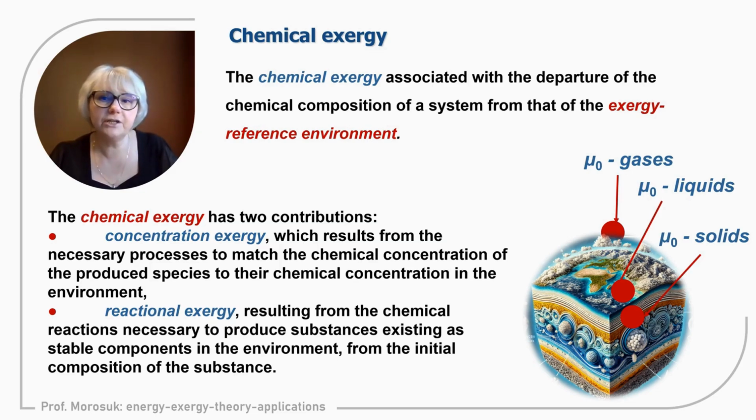Concentration exergy is associated with the work that can be produced when the system is brought to equilibrium with the environment, when the same substance exists within the thermodynamic environment. And reaction exergy is associated with the work that can be generated or supplied in order to generate a substance that does not exist in the reference environment but exists in real life.